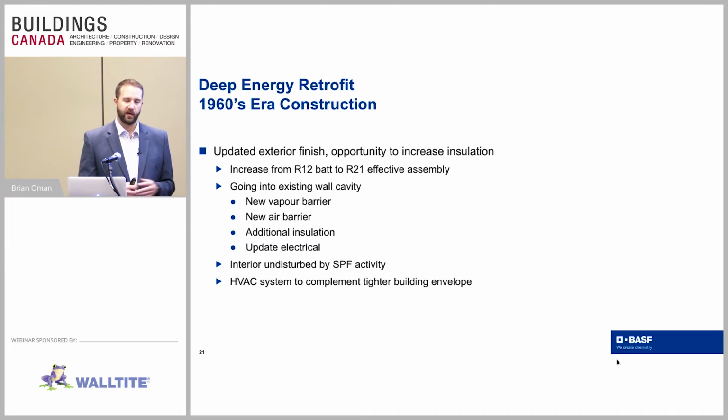The other thing to talk about is the HVAC system. I know Chris talked about it, but working with an energy advisor at this point is also a key point, to make sure that the existing HVAC system is going to be adequate for what this energy retrofit is going to provide. We may have a greatly oversized heating or cooling system for the home once this retrofit is done.